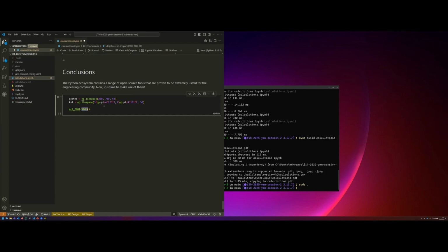Sometimes we want to check these code equations against databases of experimental results. But when we do that, of course, we are operating with observed or measured values. So, of course, we declare partial factors as one, but we also want to operate with average and not characteristic values, for example. Yeah, that's a good point.